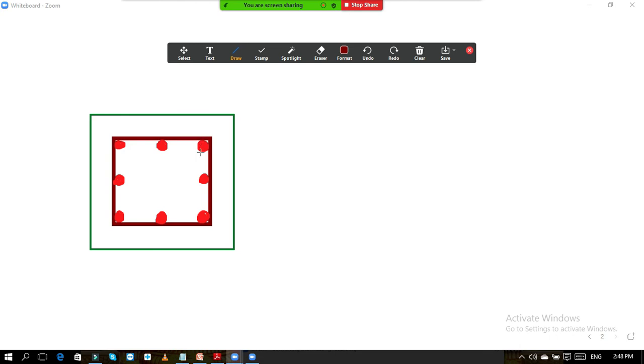In addition to this, you can also provide the stirrup in this way. For these internal bars you can provide the stirrup separately like this also. So this is the reinforcement which we are going to provide. If you don't show this stirrup, then it is also okay. This design is also correct.